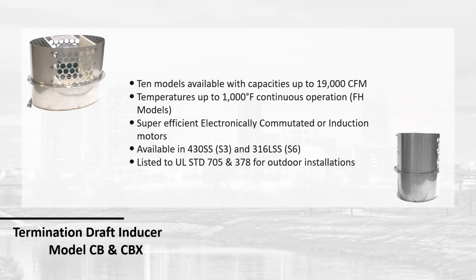The fan is rated up to 1,000 degrees continuous. If you have a 1,000-degree boiler system, you have a problem. Boilers today just don't have those types of elevated flue temperatures. However, we do this for 2 reasons. One, we do some industrial projects, kilns, ovens, that type of thing. Secondly, UL 103 is listed for 1,000 degrees. So we went ahead and got our 1,000-degree listing to match the vent system.